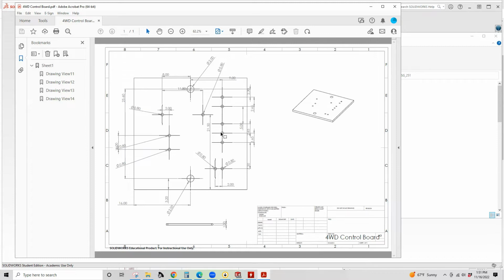So there are a few components that go here. One is the 3-pin connector, which we use as the motor connection. So even though we only have 2 active pins, the 2-pin connector next to it is where the LED goes. The resistor goes across here. You have the 2-pin power connector down here. So this goes over to your battery box. And these two ideally are mounting holes. This last one being the switch to engage power.